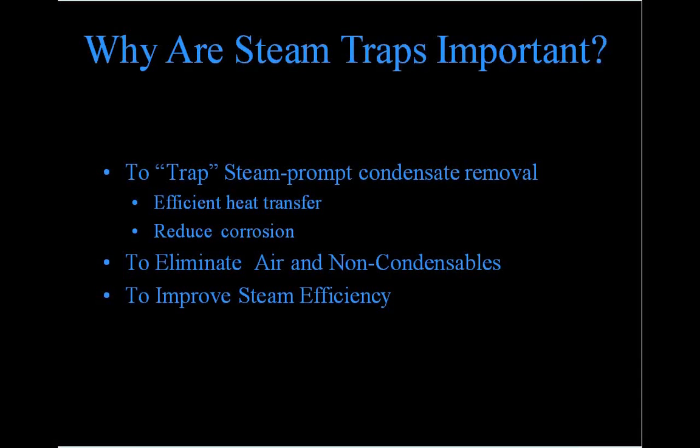And then also, you want to eliminate air and other non-condensables. As all of you know, air is a wonderful insulator, but that will keep the steam from doing its job, whether, again, you're heating up a product or a food or even just a liquid in a heat exchanger. If you have air, that's going to insulate and block some of those efficiencies.